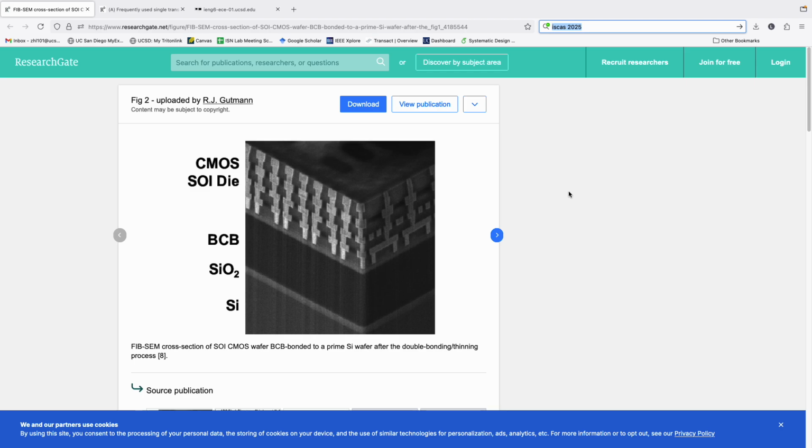So after layout, your circuit's performance will degrade or change, at least with respect to your schematic design. That's why after you lay out, ideally you need to do post-layout extraction and run the simulation again, make sure everything is correct, and then you can send the layout to the foundry, for example TSMC, GlobalFoundries, and in our case, I guess it's SkyWater's, to let them manufacture the circuit for you.